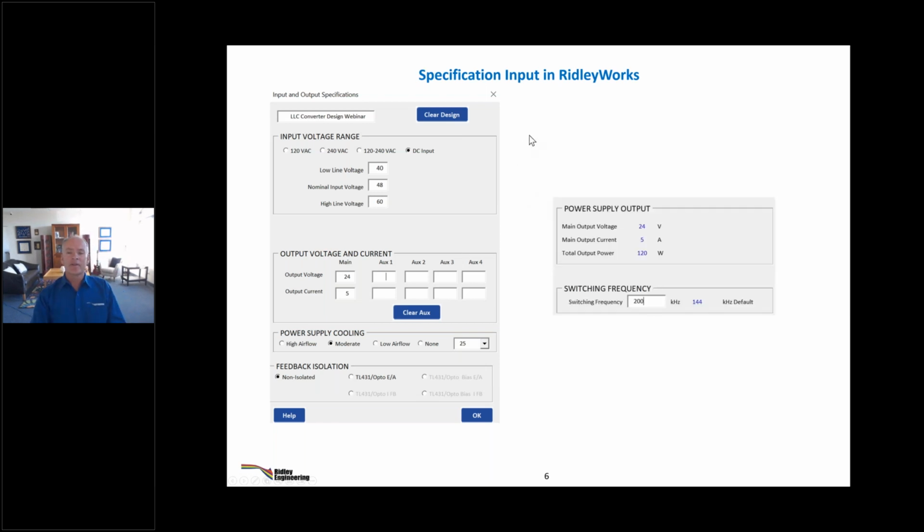When you design the LLC, you want to decide what switching frequency you use. And I think I'm a little bit different from a lot of people doing the designs. I like to set up my minimum switching frequency. I know a lot of design processes, they go for where the second resonance is, but to me, the minimum switching frequency is what is going to determine the size of the converter.